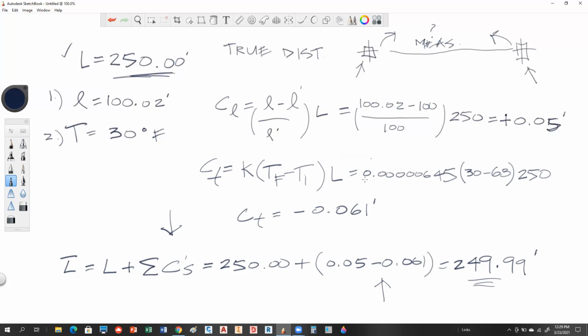Yeah, because what happens is these guys swap sign in a layout, okay? So this positive goes to a negative, and this negative goes to a positive. So for a layout problem, you're laying out what? 250.01, right? See the difference? It wasn't very much in that case, because again, the one error compensates out for the other, essentially.